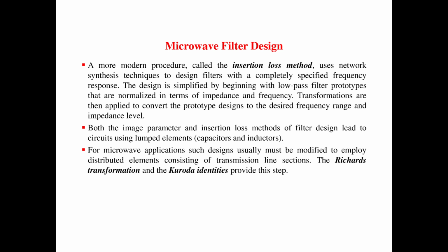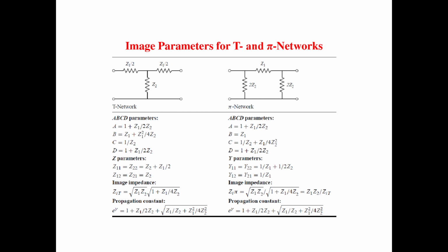Both the image parameter and insertion loss filter designs lead to circuits using lumped elements. For microwave applications, such designs are usually modified to employ distributed elements consisting of transmission line sections. The Richards transformation and Kuroda identities provide this step.